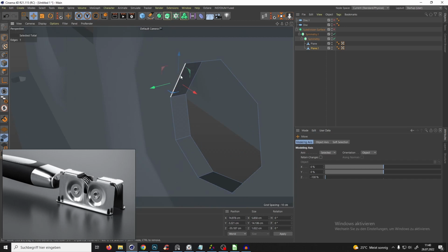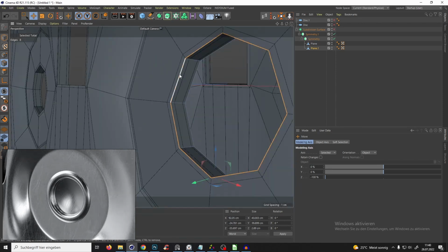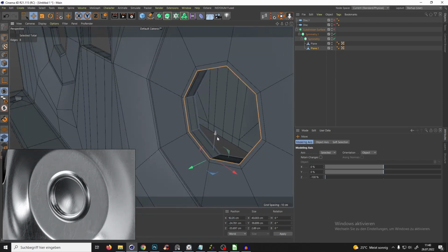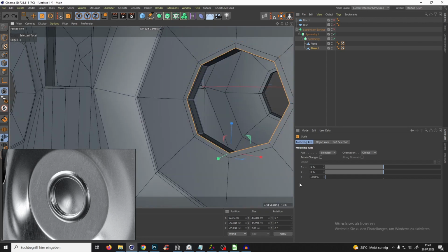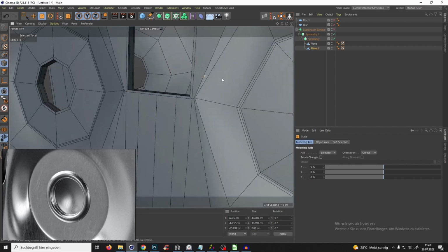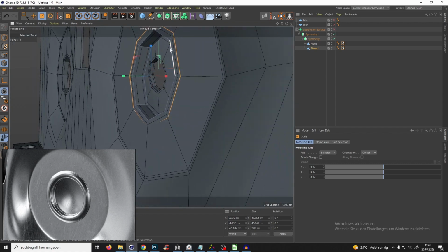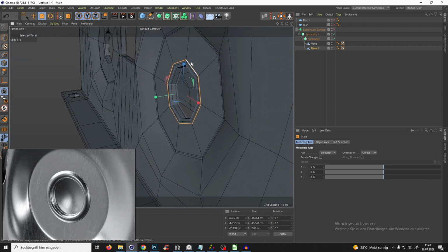And now we want it to go a little bit around, you know. That's very easy. We just select all those edges here. Let me press NB, maybe it's clear. And just T for scale, and we scale them a little bit outside. But we have to bring the Z-axis again to 0, so it scales from the middle, and we just need those two axes with control click, and we bring it down. So yeah, later we can give it thickness.